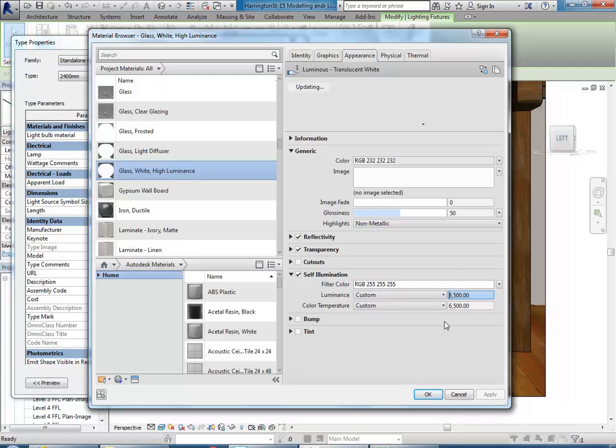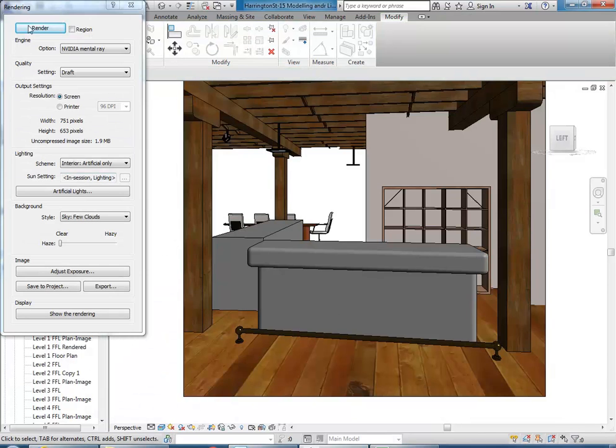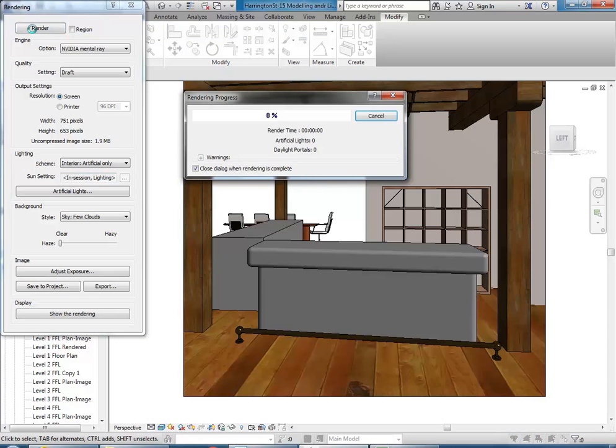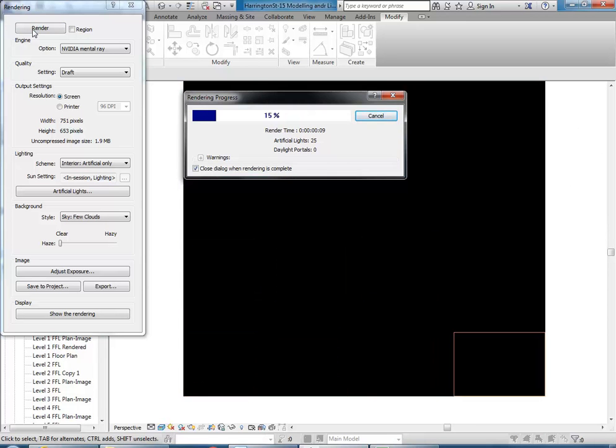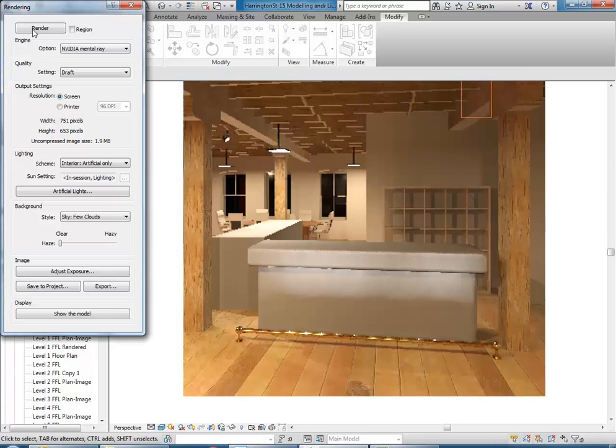Okay, so yeah, it's lucky mental ray does image-based lighting. In other words, lighting with a material. So the material, if it's a glowing material, will emit light, which is, yeah. No, it's a bit painful. Yep. So there we go. Okay, so then as you improve the render quality, that will do even more. But it does nice lighting, so you can see it on the brass, that's working pretty well.